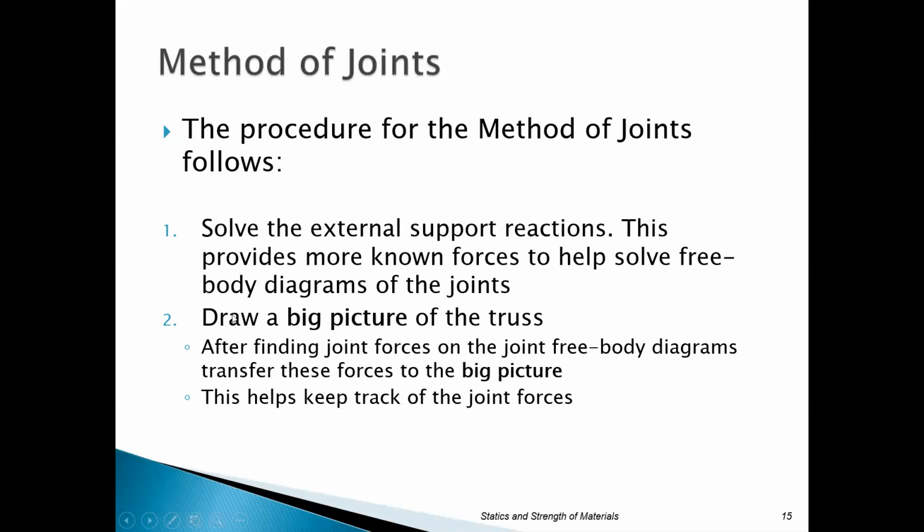And then Tom talks about drawing the big picture of the truss. So what he's saying is after you've found joint forces on a joint free body diagram, you're going to transfer that to the big picture. You kind of have an overall picture of your truss, and you can start putting your numbers on the members and whether they're in compression or tension. Okay, so this definitely helps you keep track of joint forces.